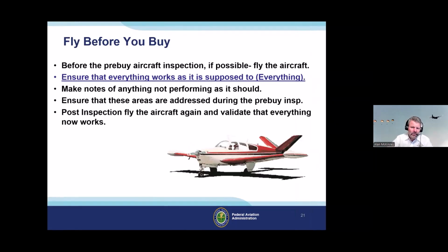So now you are going through the pre-buy, or actually, let's back up. Before you do the pre-buy, if you can, grab the current owner and let's go fly this. And before you go fly, review the flight manual, any supplements, weight and balance, equipment list, all that good stuff. Get a feel for what this aircraft looks like and what's supposed to be going on. Go fly it. Turn on, off, operate every darn thing you can operate.